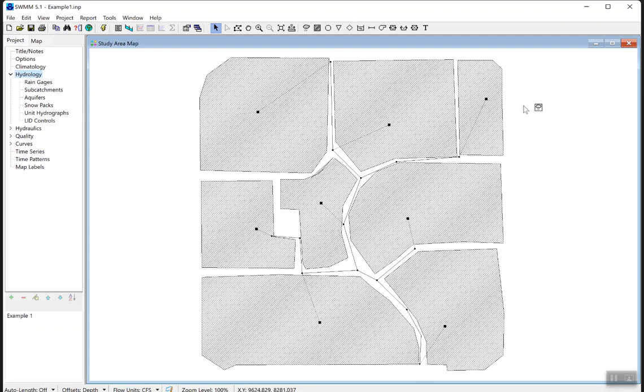So very briefly about the hydrology part. Any SWMM model that is built to simulate storm networks should contain 4 different components. It should contain the rain gauge, which simulates the rain event. It should also contain different catchments, which correspond to different land uses.